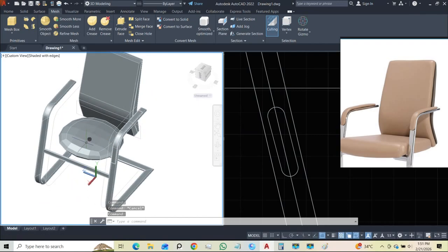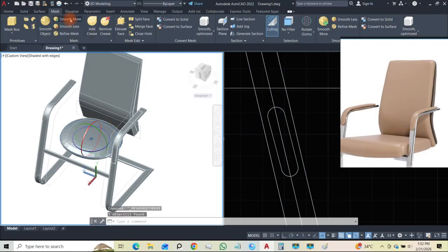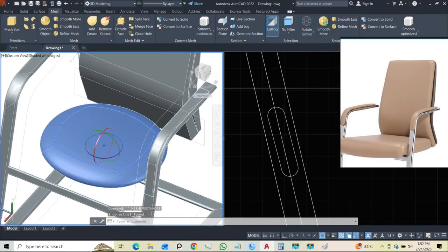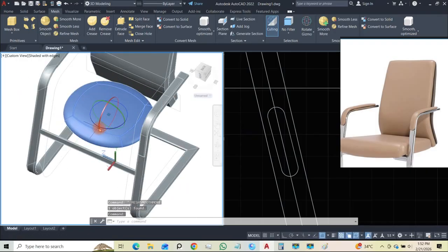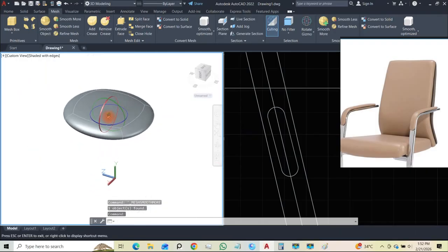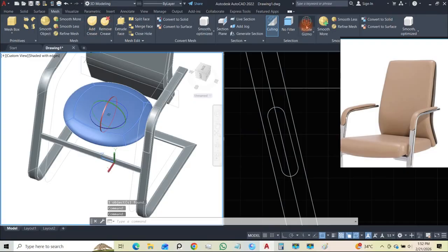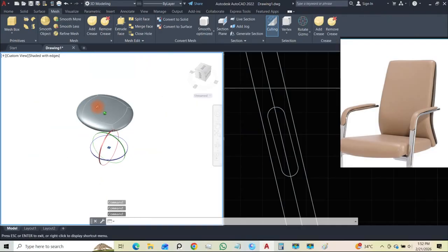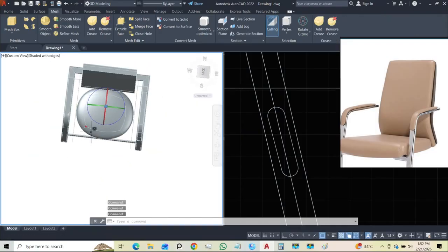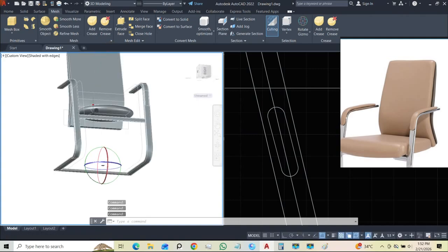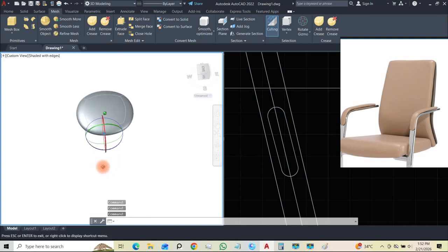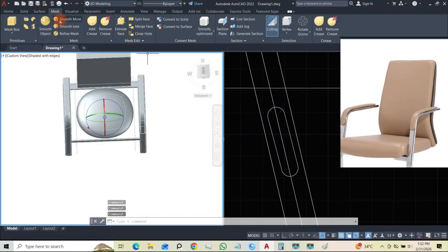So one more thing I want to do is smoothen this object. So I'll click on no selection filter, and then I'm going to smoothen more and smoothen more, and now this is smooth. But now the thing is, I've over smoothened this. If I try to select, okay, so that works. So what we can do is I can select this point and this point. Once you have them selected, I can come all the way to my move.